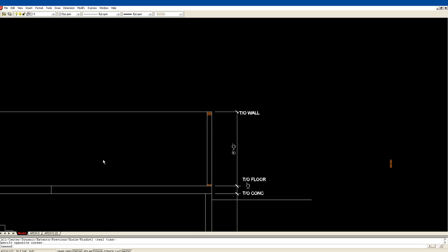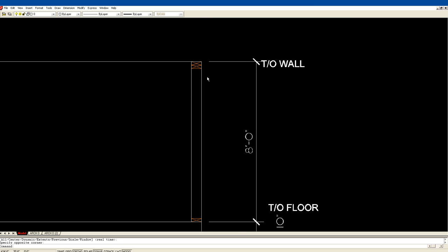And of course, they'll have the wall laying down on the floor, and they will apply the top plate, the bottom plate, the studs in between, lay out all their windows and doors and so on and so forth. Stand it up, okay, brace it in place, and then lock all the sections together with this locking plate at the top. Okay, so these studs that are in between here run from the bottom to the top. They are less than 8 feet, obviously, for an 8-foot high wall. You know, 82 inches.